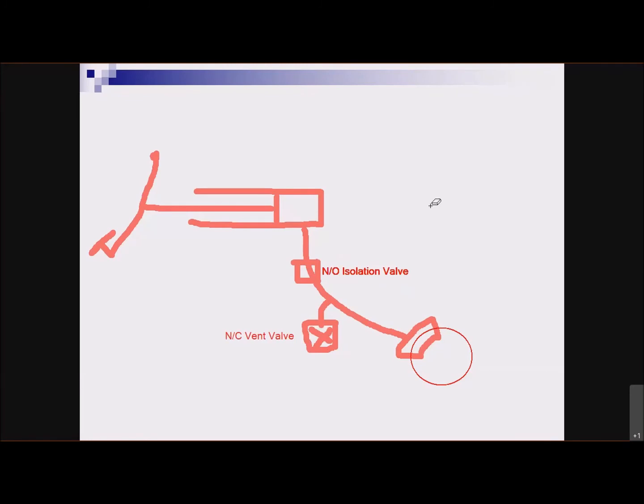So you're driving down the road, 4-channel ABS. So each wheel has its own wheel speed sensor, and you step on the brakes. And how does the computer know that you have a lockup situation happening? A couple ways. So one really obvious way is if the wheel speed sensors suddenly are seriously mismatched.